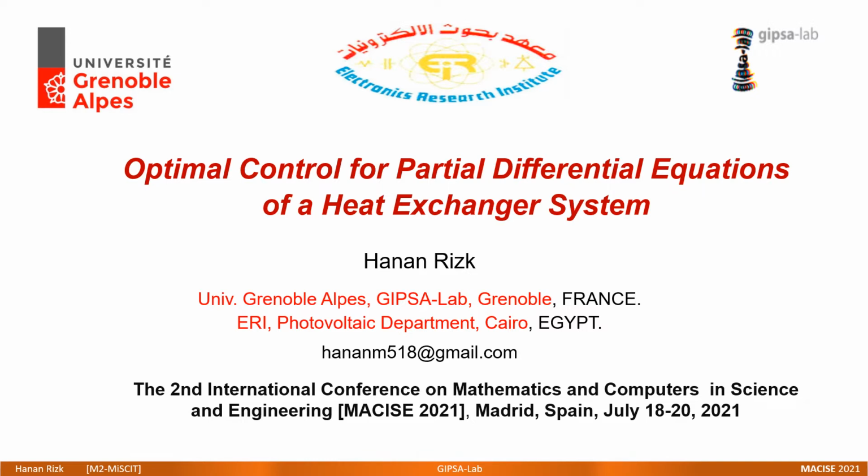Hence, the system safety of the double pipe heat exchanger depends on the behavior of the temperatures of the hot and the cold fluid, which is modeled by two first-order coupled hyperbolic partial differential equations, as we will see after, that represent this complex system we handle.